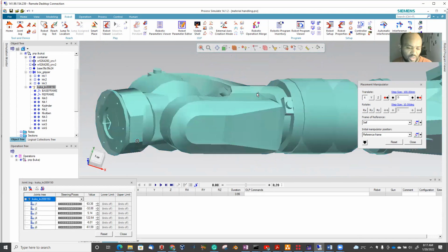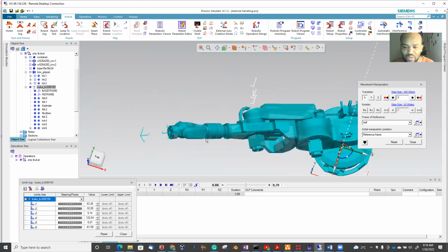Yeah, that's a convention. Otherwise, if everyone uses whatever he or she likes, then it is a problem. So in order to have a convention, this is a standard. There is the DH, which we call the Denavit-Hartenberg convention, which says it's recommended. It's a convention or a standard. So assign the z-axis along the axis of rotation. It is in the local coordinate. It is not in the global coordinate.